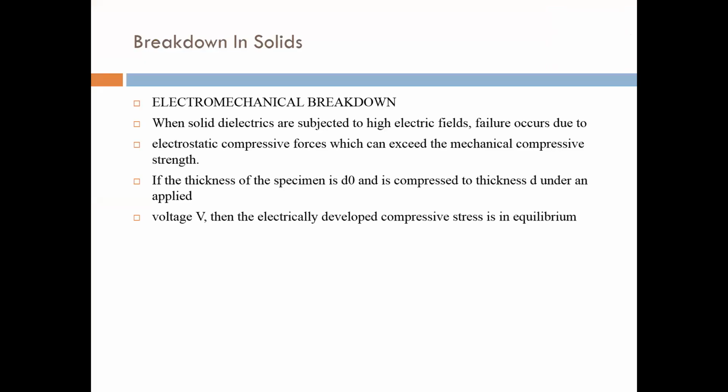Firstly, the electromechanical breakdown. This happens due to high electrical fields. When we apply a high electrical field, the failure in the case of a solid occurs due to electrostatic compressive forces which can exceed the mechanical compressive strength.